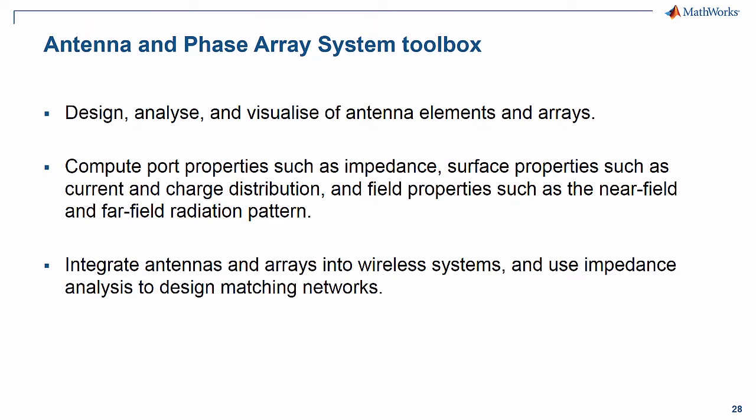For this purpose, we have two products, the Antenna Toolbox and the Phased Array System Toolbox, where you can design, analyze, and visualize the antenna elements. You can compute the port properties such as the impedance, surface properties, check the near field and the far field radiation pattern. You can also integrate the antennas and arrays into wireless systems and use impedance analysis to design some matching networks. So with these two toolboxes combined, let's see what things we have.